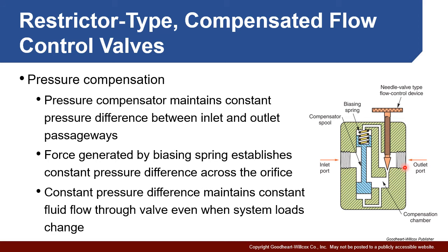And essentially what it does is maintain the pressure difference. If the pressure was to go up, this closes off, causing a pressure drop, and it keeps the pressure the same, at least the pressure difference, I should say, on either side of this. If the pressure difference is the same, you're going to get the same flow rate.